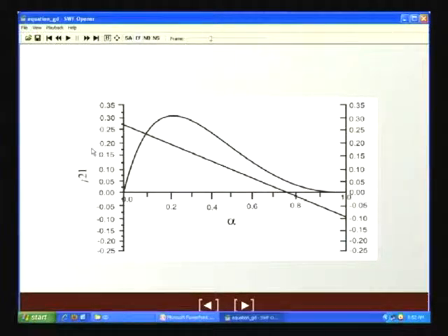Because this curve we have drawn is for a particular u infinity and n, for the bubbly flow pattern. Accordingly, we have selected u infinity and n. Therefore, the point of intersection should lie in the bubbly flow pattern. When does bubbly flow occur? Low gas, high liquid. So, we will always have the point of intersection between alpha equals 0 and alpha equals 0.3 or something of this sort.